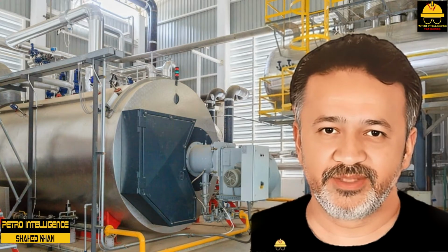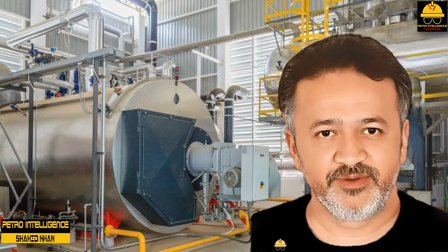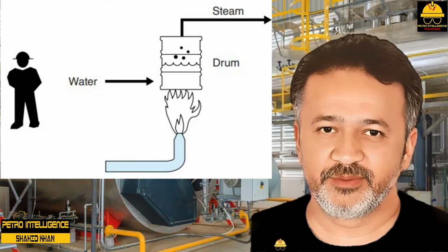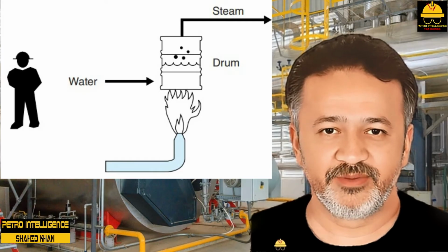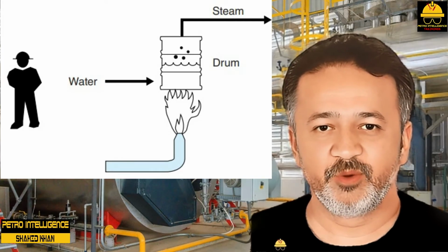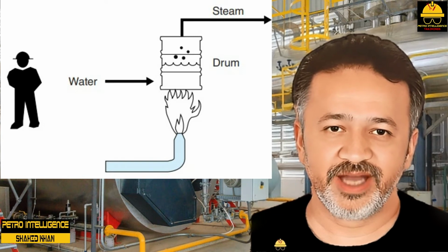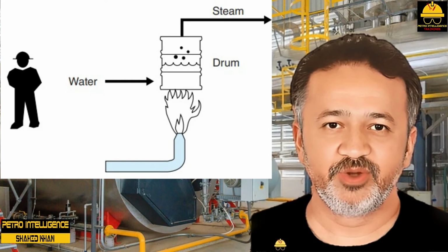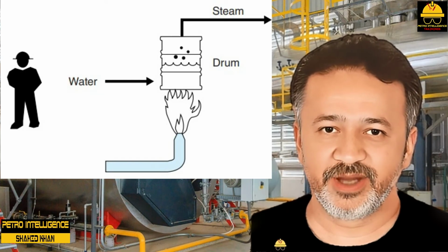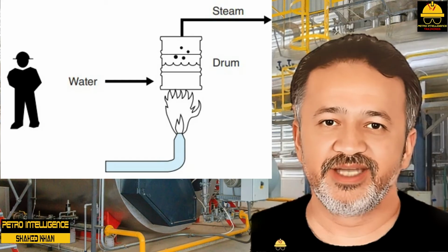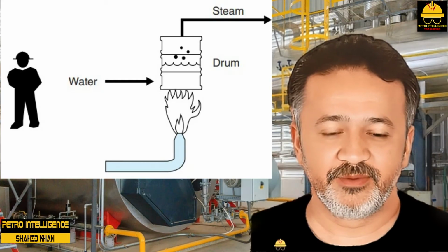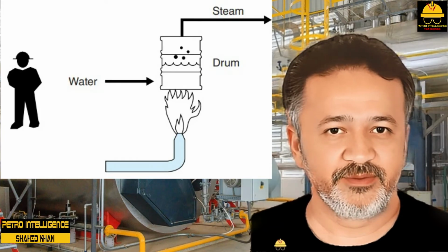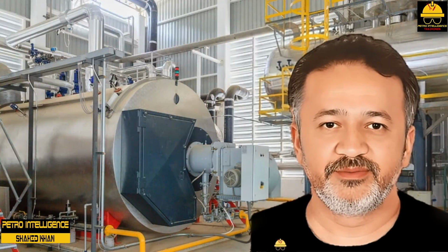Boilers use a combination of radiant, conductive, and convective heat transfer methods to change water to steam. A simple boiler consists of a heat source, water-containing drum, water inlet, and steam outlet, as shown in the picture. As heat is added to the drum, the temperature increases until the water boils. As the steam rises, it is captured in a line and sent on for further processing. Factors that affect boiler operation are density differences for internal circulation, pressure, temperature, and water level.